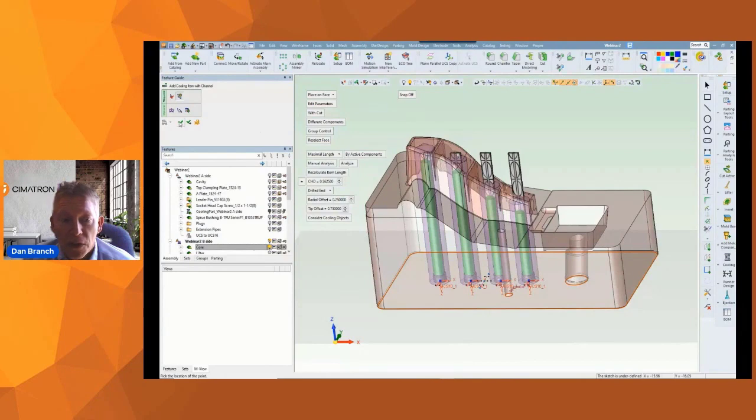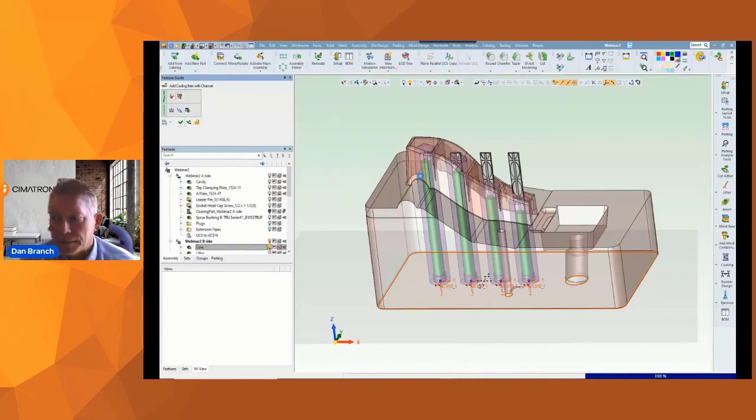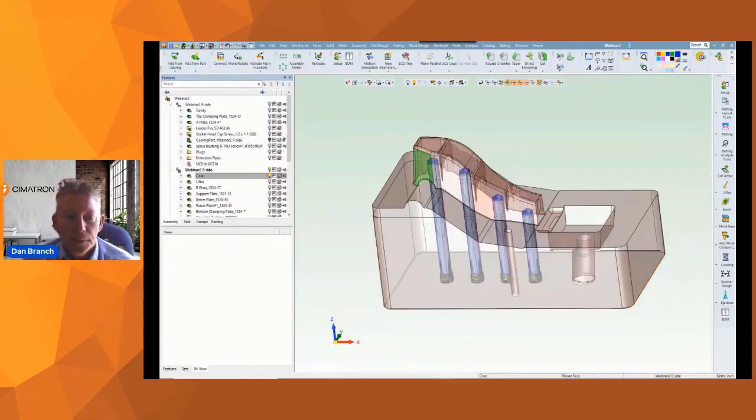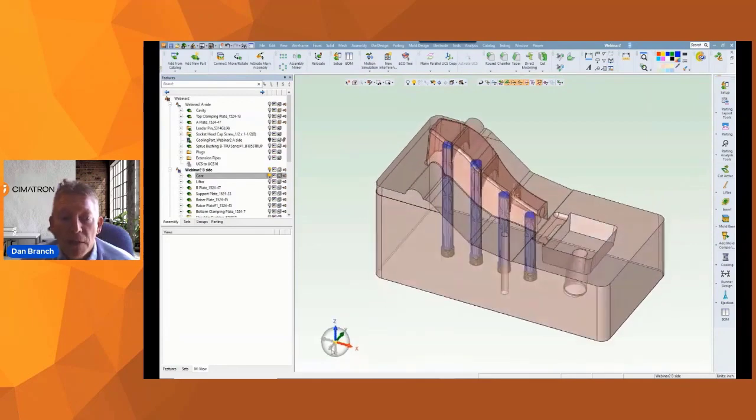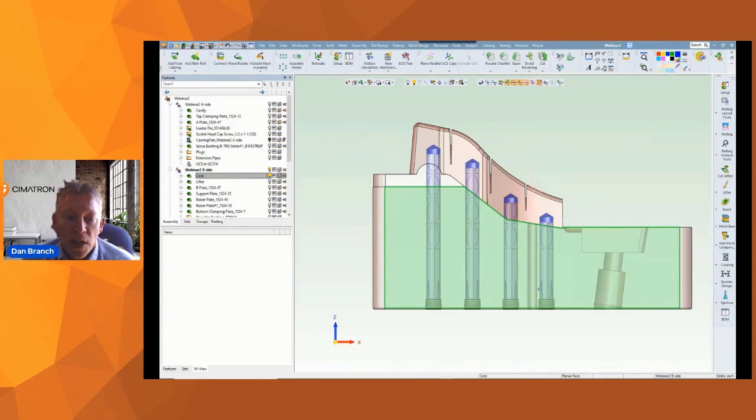The baffles themselves in gray, I know they're still showing too long, but really that's just a preview. I'm looking at the tubes. I trust the function to be correct, so I've already hit approve here based on those channels, and each catalog baffle is now going to be trimmed off appropriately to fit the water channel that it sits in. So I know each of these baffle channels is safe in every direction to the core geometry. And next, I just need to add some connecting lines, either by adding another component with a channel like we did, or by using that circuit method that we started with.